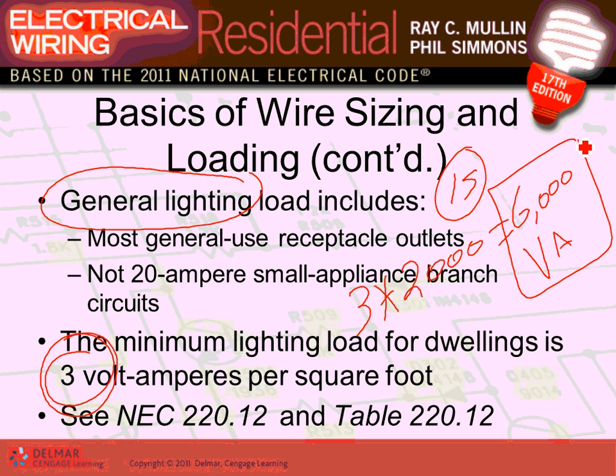This is how much volt-amp the NEC code book allocated for all your receptacles, general use receptacles, and lights. Done. Where does this number come from? This number is from Table 220.14, which we will also be using for a couple of calculations. We'll be using calculations, especially for people like Matthew and Derek, who have not used a calculation on these tables.